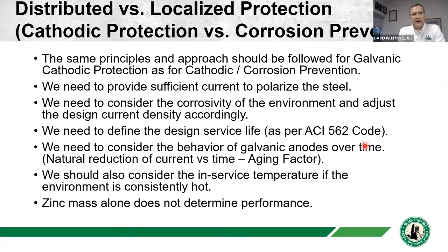Because they're galvanic and there's a limited potential difference between the zinc and the steel, you will polarize the steel more with more anodes. Obviously, that's what we're doing with the distributed system. You're polarizing the steel sufficiently to meet full cathodic protection criteria.